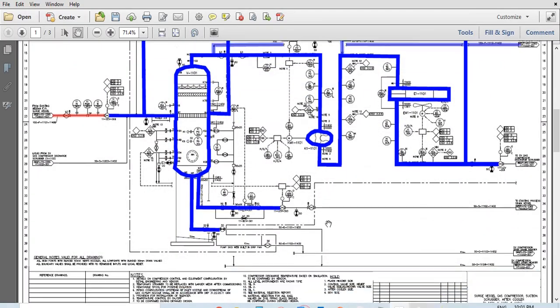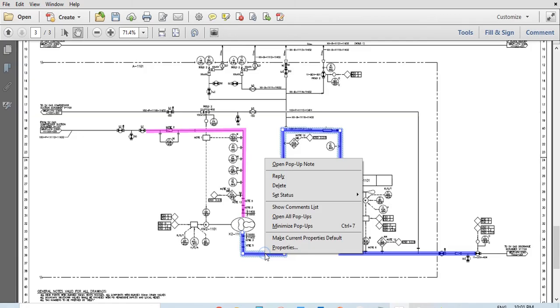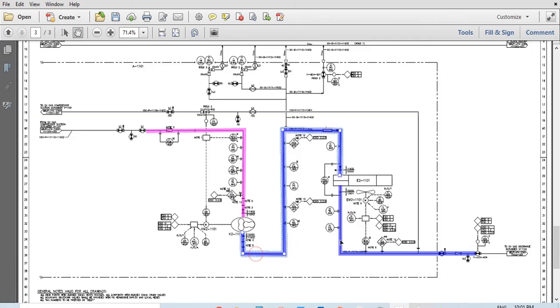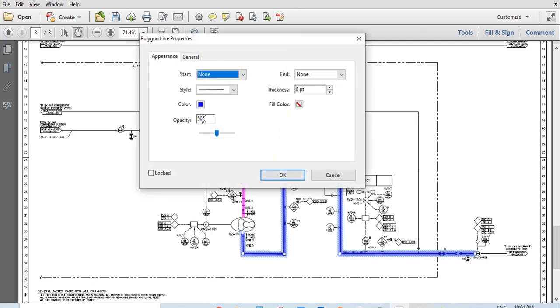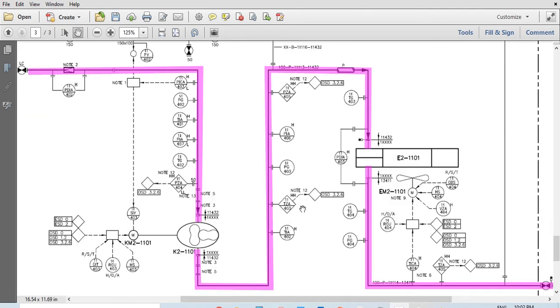So this that I've done, you do it for another isolatable section like this. You run it all the way through. We count from here, here, here, count all the equipment, count all the instrumentation, just like that. This is the same isolatable section. Okay. Yeah, so this is another isolatable section and you can count everything.